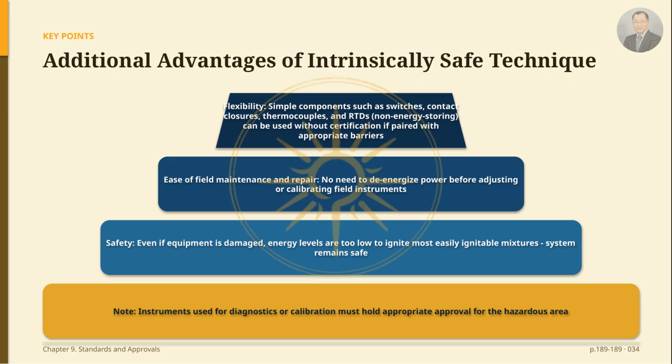First, it offers greater flexibility because this technique permits simple components such as switches, contact closures, thermocouples, RTDs, and other non-energy storing instruments to be used without certification, provided they have appropriate barriers. Ease of field maintenance and repair are also advantages. There is no need to remove power before adjustments or calibration are performed on the field instrument.